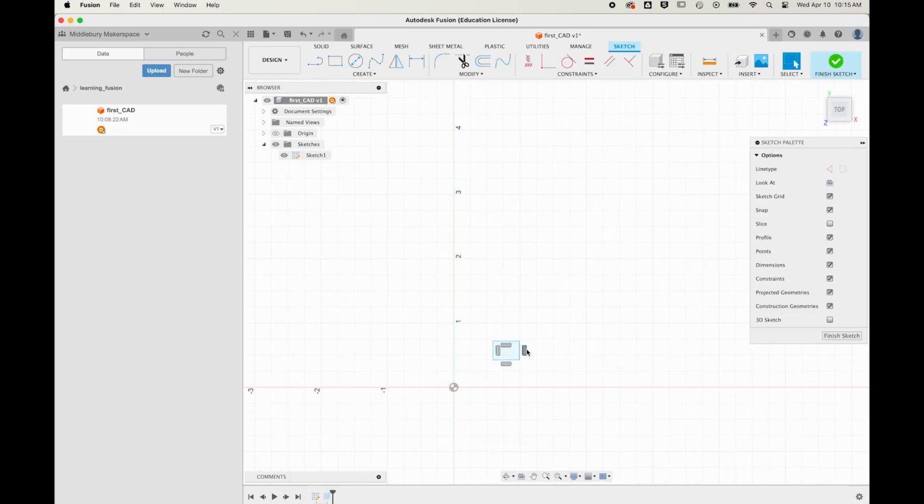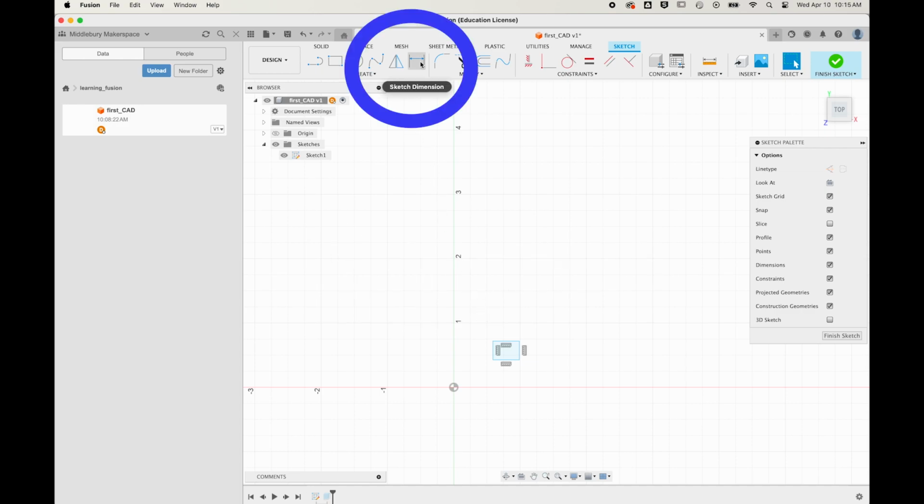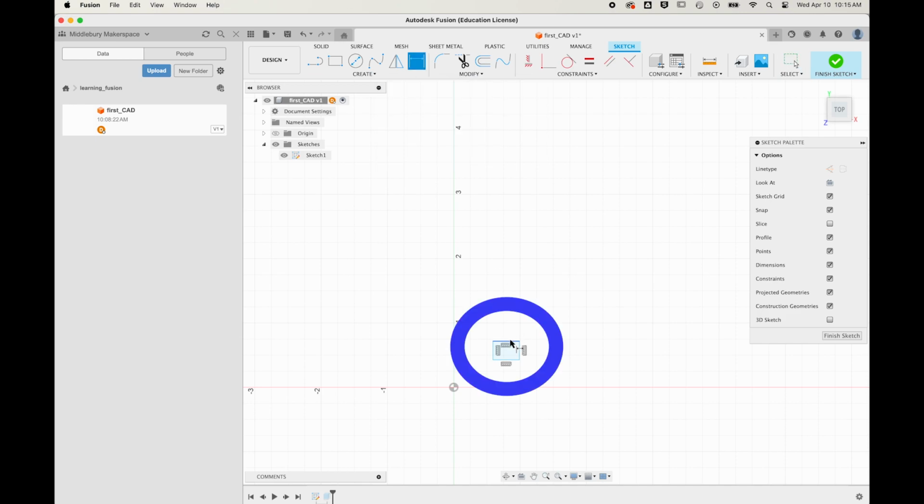Double-click on your sketch one more time, and now let's dimension some of these parameters. Dimensioning a parameter means precisely defining it with a number. And it's not just precision, it's also the notion of locking part of your sketch into place so that it doesn't change anymore. How do you do it? Click on the Dimension tool, come down to this top edge of your rectangle, and click on it using the Dimension tool, and then move your mouse up and place your dimension somewhere above your model.